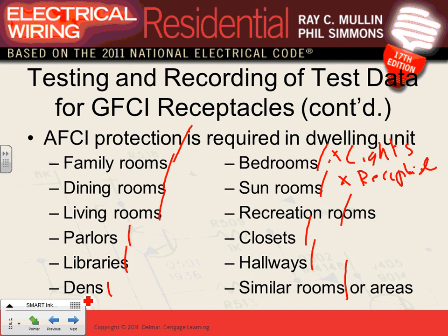So the way I understand it, guys, this is always needed in places where there is no GFCI. Think about it. Is there a kitchen here? GFCI. No, it's not here. Is there a bathroom here? No, it's not here because it needs GFCI. Laundry room? No, not here. Unfinished basement? No. All these are GFCI. Outdoor receptacles? No. Garage? No. Crawl space? No. Can you guys see how you distinguish between the two? Where GFCI is needed, AFCI is almost not needed at this moment.